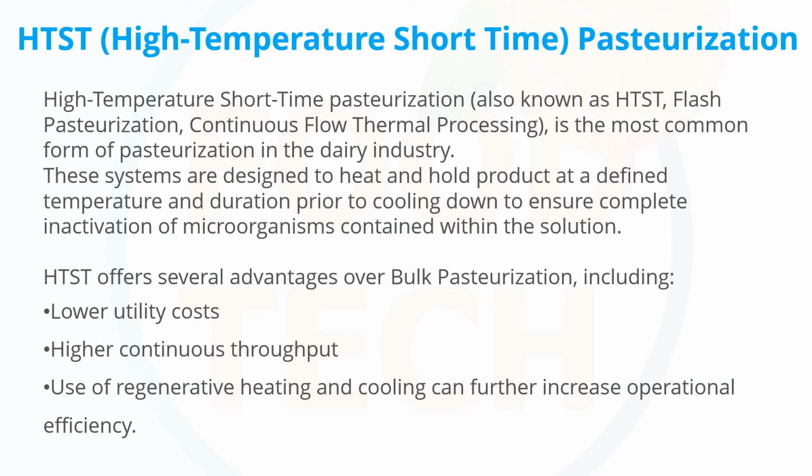High temperature short time pasteurization, also known as HTST or flash pasteurization, is a continuous flow thermal process. It is the most common form of pasteurization used in the dairy industry, and this system is designed to heat and hold the product at a definite temperature for a set duration, then cool it down, to ensure the complete inactivation of microorganisms in the product.